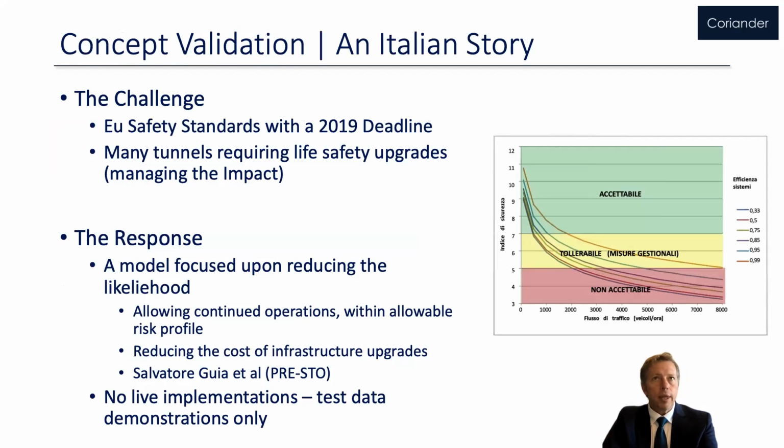So with that context, I'll jump back to my Italian story. The story in Italy at the time was that the European safety standards were being implemented with a 2019 deadline. And in Italy, there are a large number of old and aging tunnels that all met the threshold for improved safety requirements. But with a lack of money, the standards were focused on the right-hand side of that bow tie, applying deluge, fire detection systems, smoke extraction and the like to reduce the impact component of risk.